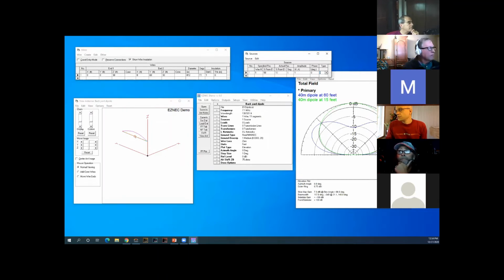Any other question, Warren? Fred, I have on occasion had the actual position shifted. Is that because I don't have an odd number of segments? That is correct. If you don't have an odd number of segments, it's not going to be able to put it in the middle. Got it, thanks. So the actual position will show you something different than 50. So if you go over to the wires menu and choose 11 segments, then it can find a segment that's in the middle, in which case you should see something like this over here.